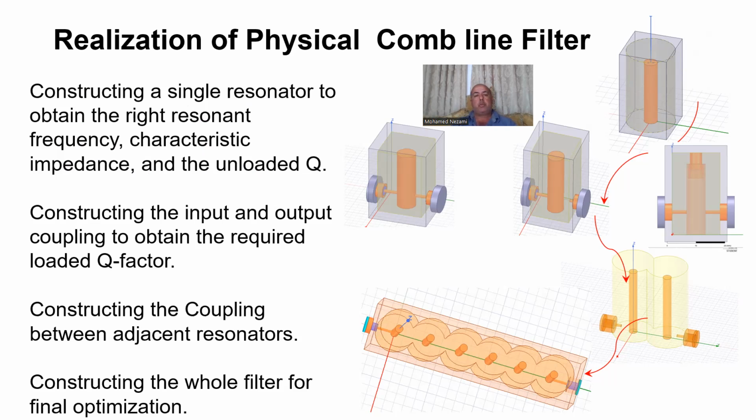I'm going to present a few of these approaches, but the first approach uses basically EM modeling, the HFSS simulator. We use the eigenmode calculator to actually model the resonance and see what the resonant frequency is and what the Q factor is. The eigenmode solver is basically a modeling technique where you can look at a structure like this without driving any waves to it, without any ports. Depending on the materials and the geometries, it calculates the resonances of this structure, and many of them, of course, not just the lowest mode, but up to a certain number of modes.